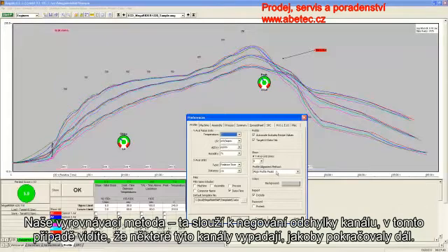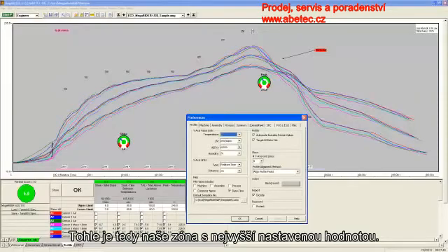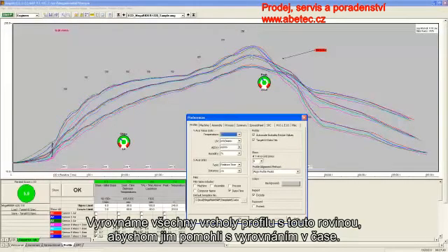Our alignment method, this is what we do to negate channel offset. In this case, you can see that some of these channels look like they go on longer, and that's because we've chosen to align the peak temperatures of all the profiles with one point in time or one point in distance, and this happens to be the end of the zone with the highest set point. So this is our zone with the highest set point. We go to the end of that zone, we align all the profile peaks to that plane to help get them aligned in time.